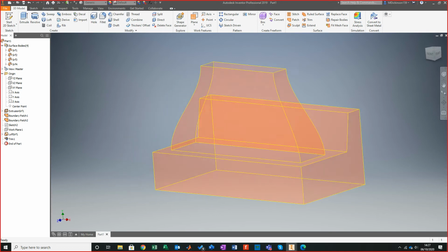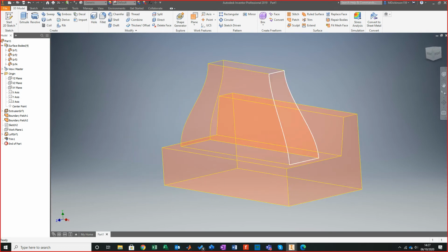So finally, what I need to do is close this off. This is going to be one way that I can generate this as a solid component. Now, what we're doing today is we're actually generating solid components two separate ways. One way is this way, where we seal, if you will, an empty box, and we fill it with volume. The other way is where we generate a profile and then we thicken that profile to a given thickness.